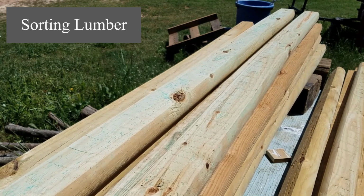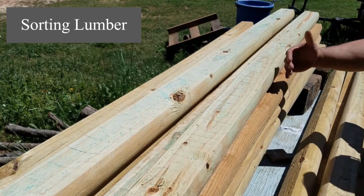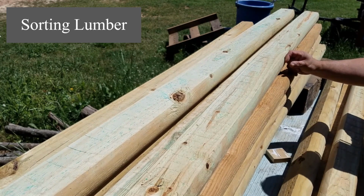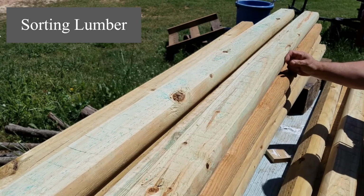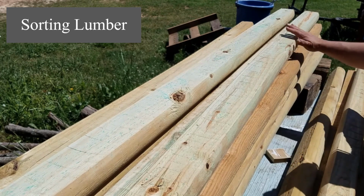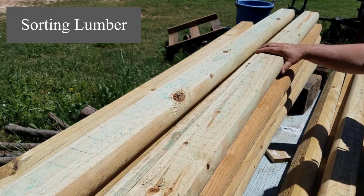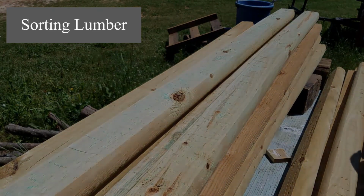Well, if you look down it, you've got a pretty good bow in it, right? From one end to the other. So it's going to have maybe a 1/2-inch crown in it. But if I need 4-foot pieces, I can cut it in the middle, and you can sight down it. You're not going to see much then. So we use the long boards, you want the straightest, and the boards that have warps and crooks in them can be cut up into shorter pieces.